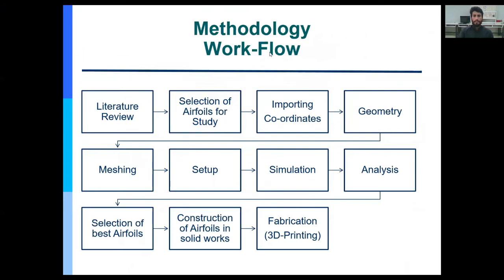This is the methodology of our final year project. This is the flow chart for this project. First, we did the literature review and then selected the airfoils for study. Then we imported the coordinates of each airfoil in Ansys for geometry purposes. And then we made the geometry of each airfoil and meshed that airfoil.